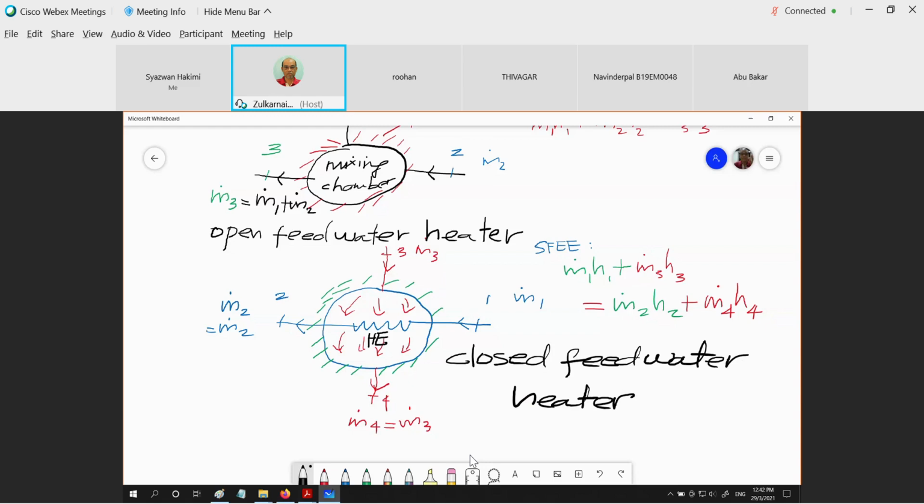Okay, remember, we have learned about Rankine superheated vapor and Rankine multi-stage expansion with reheat. Both cycles are for increasing the W net. Okay, to increase the W net. But when we incorporate this device into our Rankine cycle later, whether it's being used alone or as a multi-unit or a mix of these two units in our Rankine cycle, the purpose of using this feed water heater is to increase the thermal efficiency.